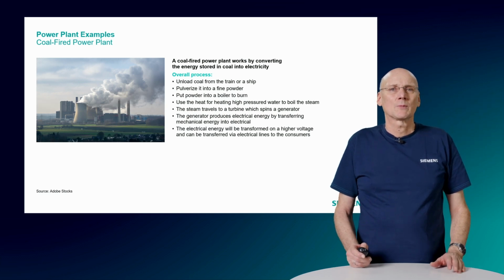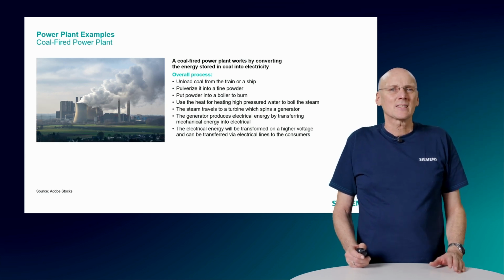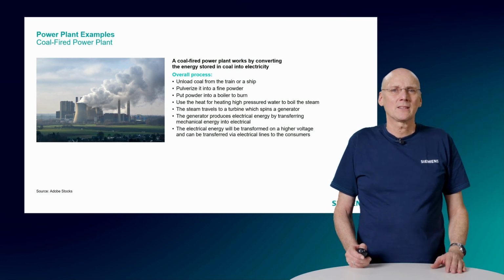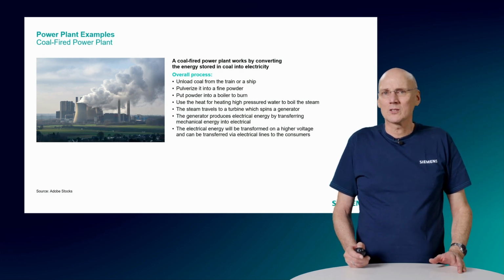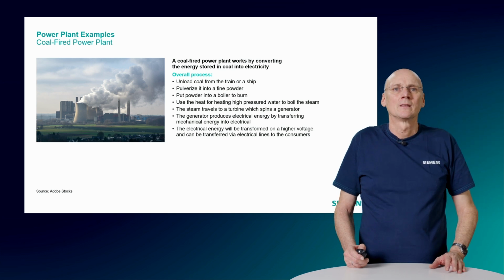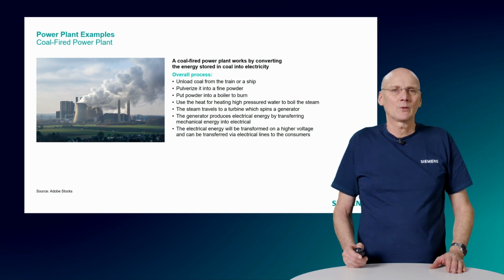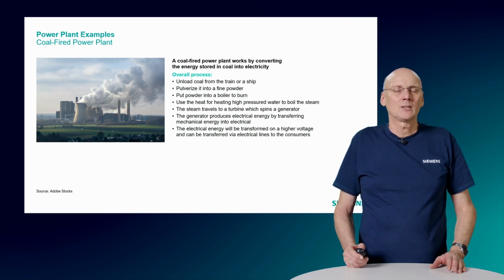So in a short summary, the task of nearly any power plant is to get the turbines and the generators rotating by heat or also mechanical drive. After the power generation, a step-up transformer is connected, which transfers the power by using inductivity of two coils, primary and secondary side, into a higher voltage with less current.